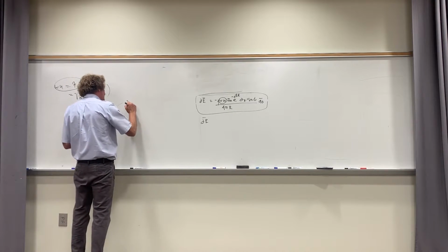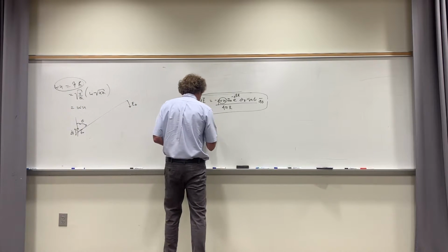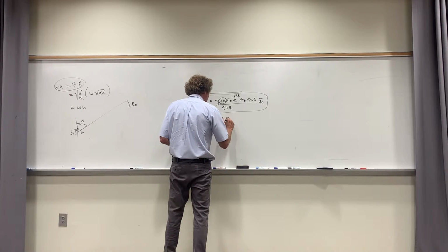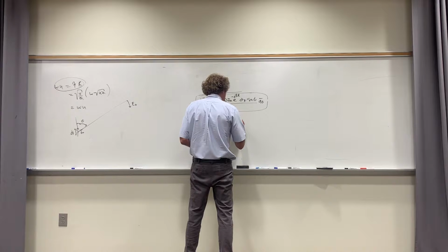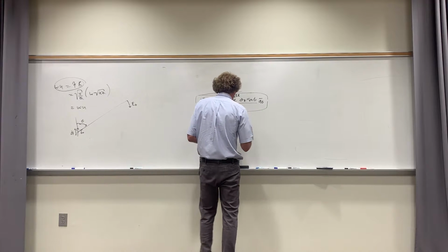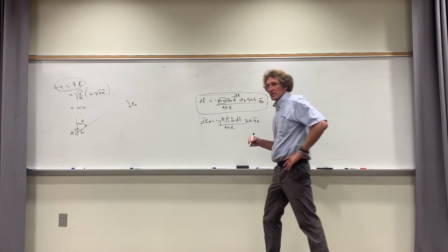He's talking about this E field, E theta, and he says E theta is equal to minus j, and then he'll have eta beta times I naught, times dl, or L, I think dl, over 4 pi r. Then he'll have the sine of theta times a theta. You all see that in his book?